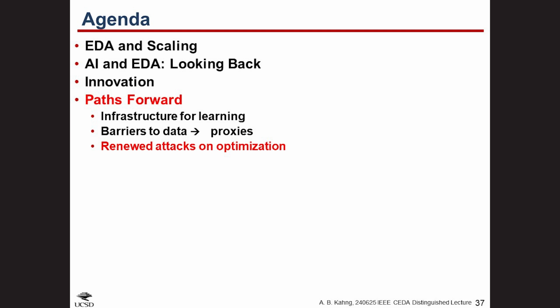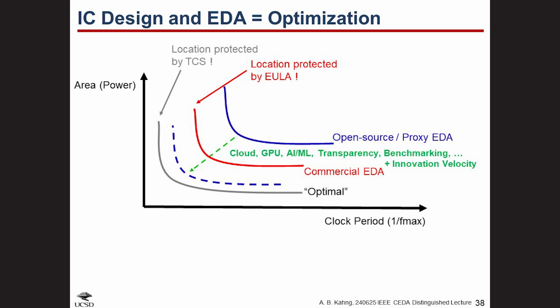The left plot here is again a PPA hockey stick with clock periods on the x-axis, and this time with power per area on the y-axis. Red is artificial, blue is a 10 times bigger target design. They're pretty close. The right plot shows that the PNR runtime is reduced by 15 to 20x with the smaller artificial design.